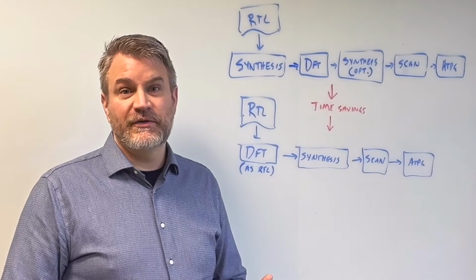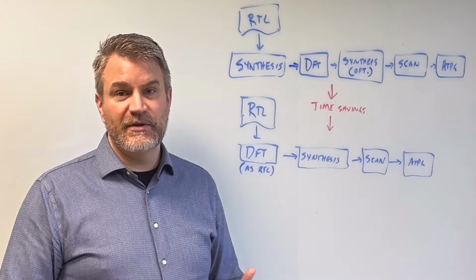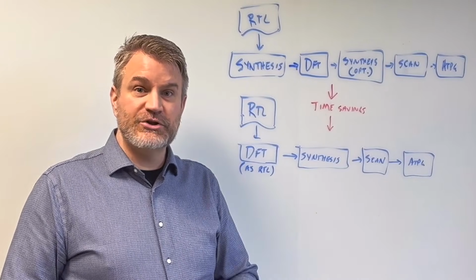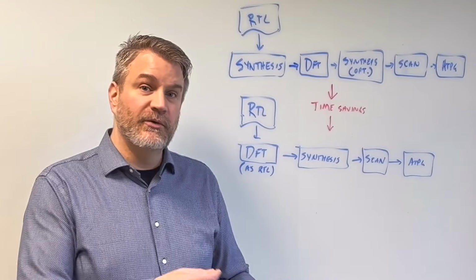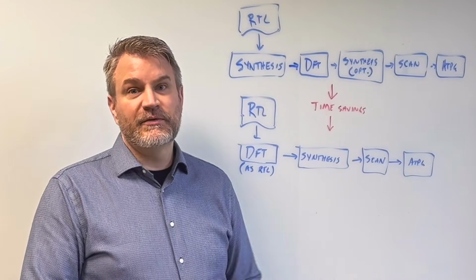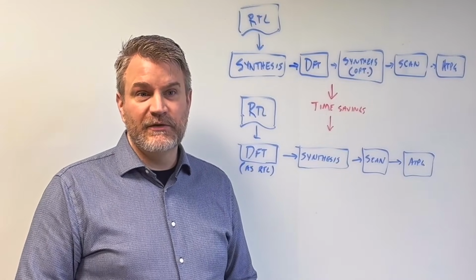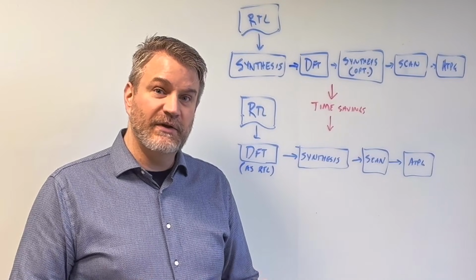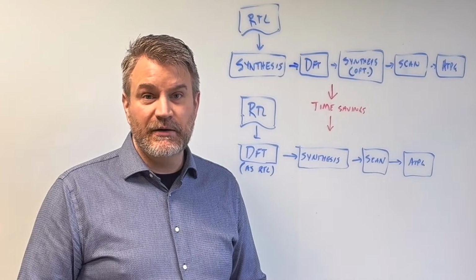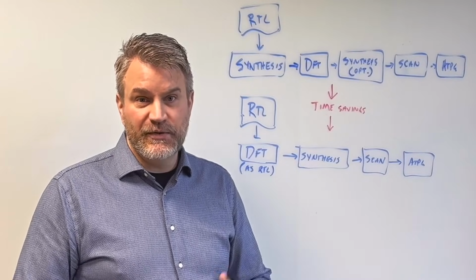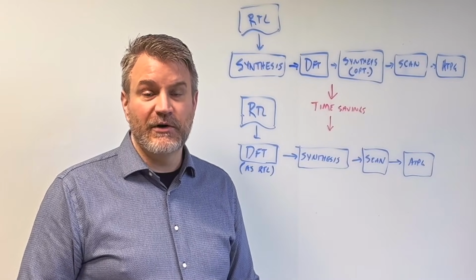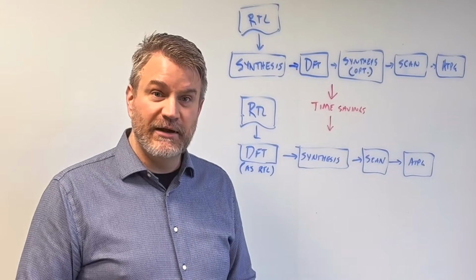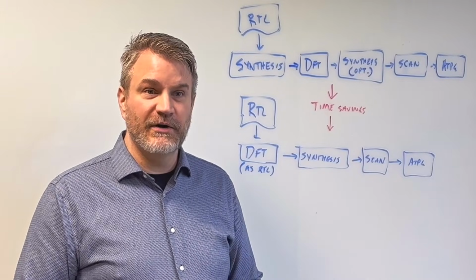For RTL test points specifically, we have the ability to inform the user of which of their RTL is suitable for test points. We can also analyze the design, identify those overly complicated areas, and call them out. And with the visualizer inside of our tool, we can cross reference and visualize those areas and directly reference the RTL.